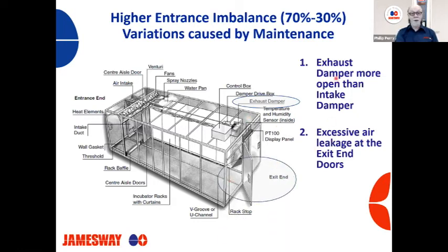Whenever you take these measurements, you need to make sure your doors are closed, because this can throw this off as well. A lot of times when I go into hatcheries, these handles are broken and you almost have to have somebody from the outside close the door to make sure it's shut properly. If there's a little air leakage here, it can cause a lower reading.